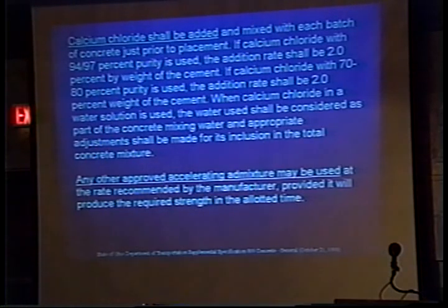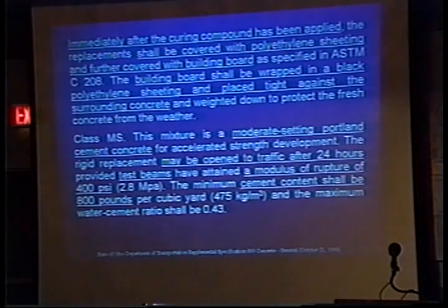But ask your ready-mix producer to give you a non-chloride accelerator. There's lots of those things available these days. I don't agree with using chloride. But anyhow, it does say here any other approved accelerator may be used as recommended by the manufacturer. Okay.